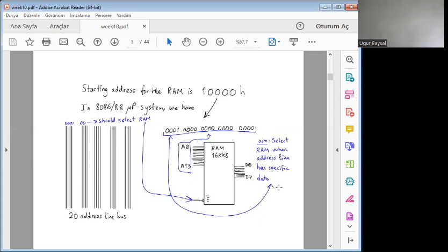Also, the microprocessor is connected to these buses through latches. So these 5 groups of nibbles of terminals represent the 20-bit address bus of our motherboard. And now RAM is placed at the right side of it, and the starting address of the RAM is given above the circuit element, and we will be utilizing the rightmost 14 bits for the RAM internal addressing and the remaining 6 bits for enabling the RAM.